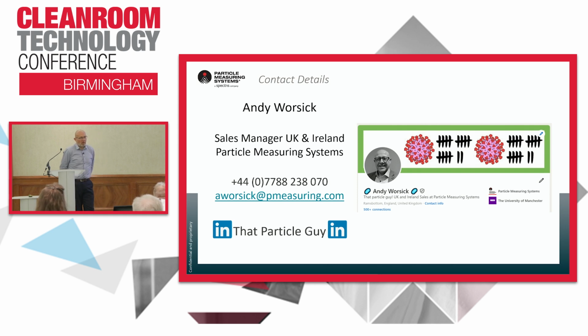I must admit, I think it's a really interesting point. It's not something I think I've ever come across or heard that comment. I think it makes a lot of sense. I would certainly say, and I think I touched on it, probe height: if you are pointing upwards, it shouldn't be close to the HEPA, because all you're really doing is scanning a small area of HEPA filter.